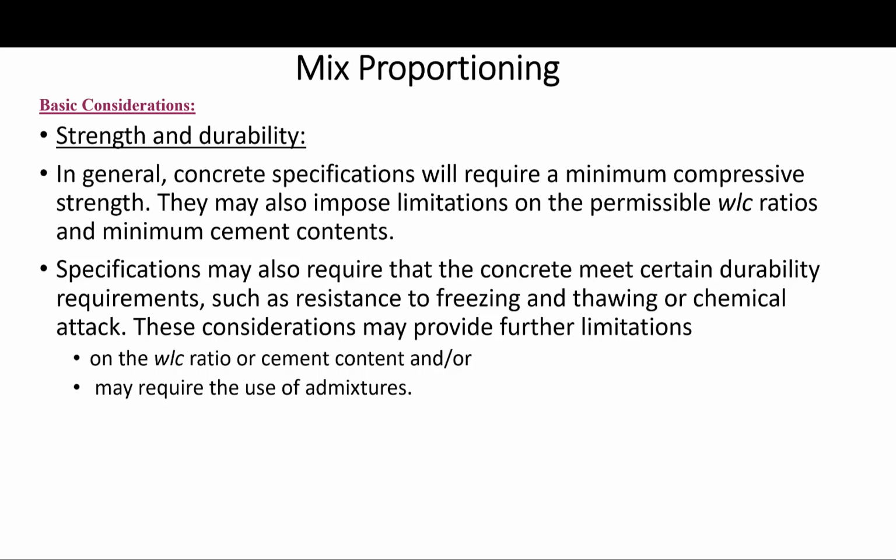The other considerations are strength and durability. In general, concrete specifications will require a minimum compressive strength. They may also impose limitations on the permissible water-cement ratio and the minimum cement content. Sometimes reducing the water-cement ratio means we are looking after durability, and the cement content is to make sure we reach certain strength at certain ages.